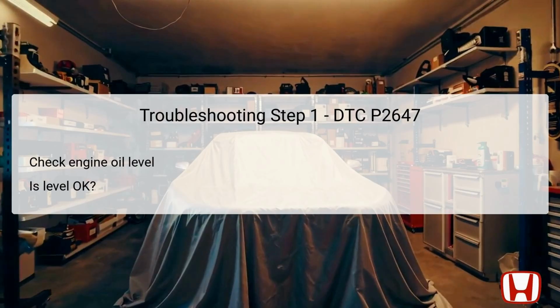On the other hand, if the oil level is acceptable, this would mean the issue lies elsewhere, allowing the technician to move on to the next step in the troubleshooting process. Ensuring that the oil is at an appropriate level is a simple yet effective method to eliminate one potential cause from the list of issues that may trigger this DTC.